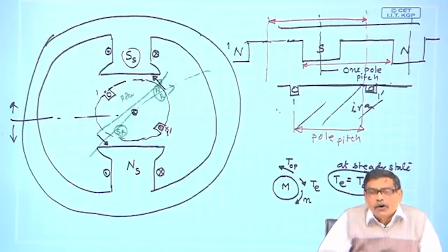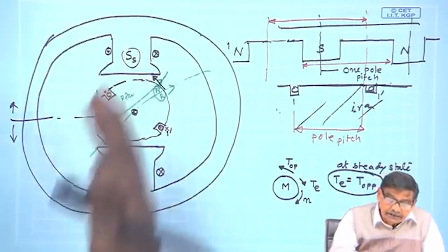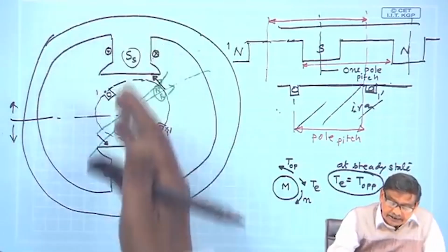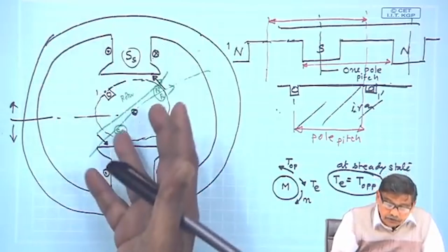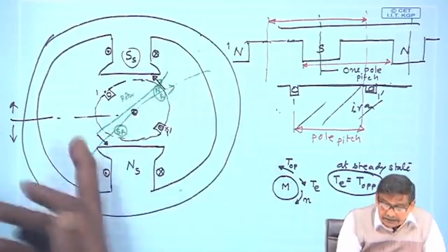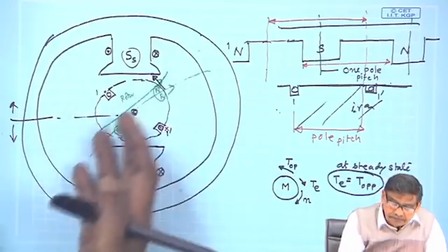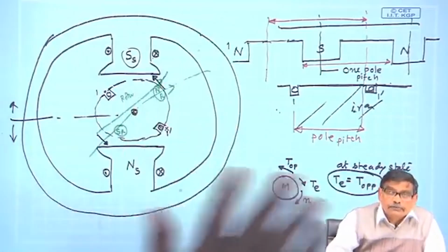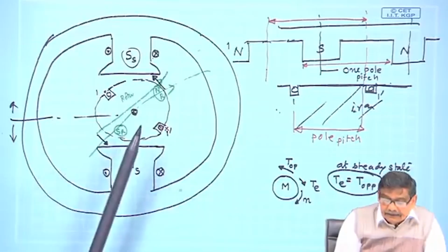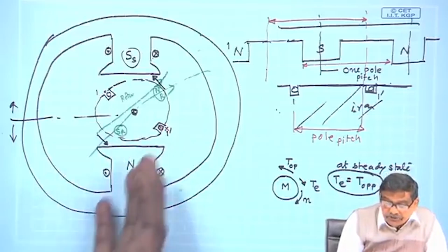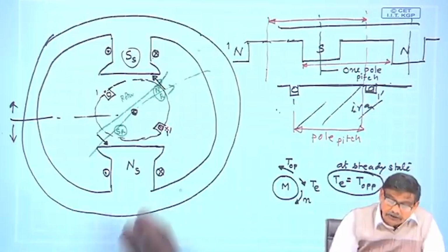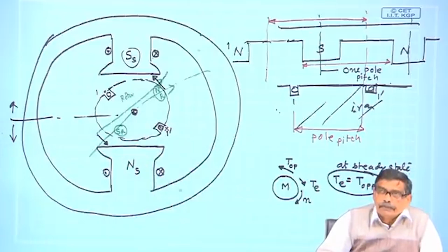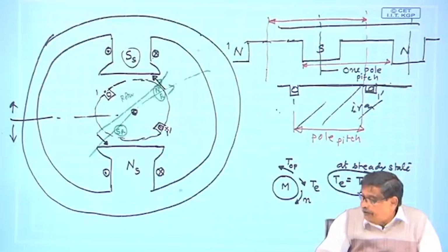The moment a coil carries current, it produces a pair of poles. If the poles are on the stator, we say okay, NS, SS. If the pair of poles are on the rotor, NR, SR. Who has created this? These currents, cross dot. And I should be in a position to clearly put the arrows of the lines of force, and then it is so simple to understand in which direction the rotor experiences a torque, and it will start moving. Understood? This is very important.